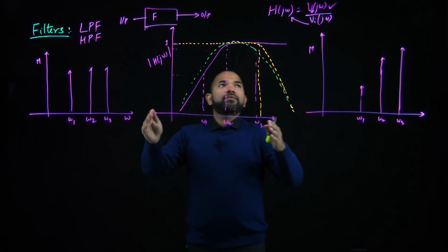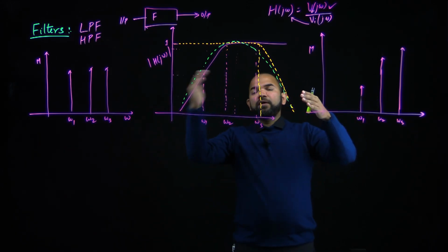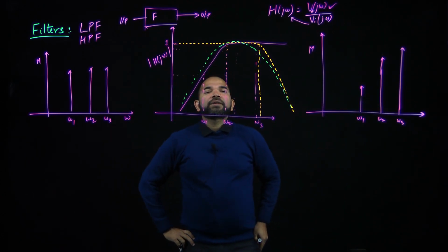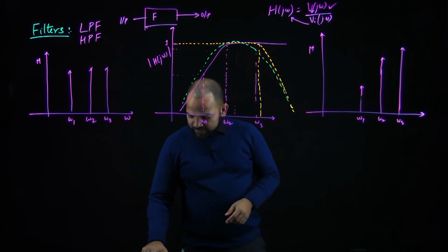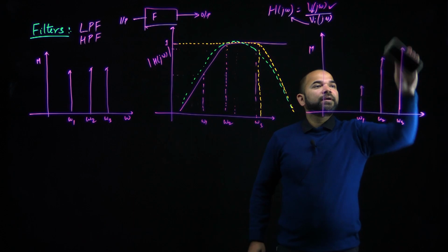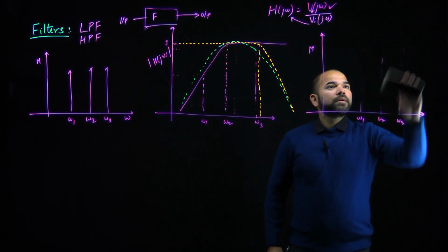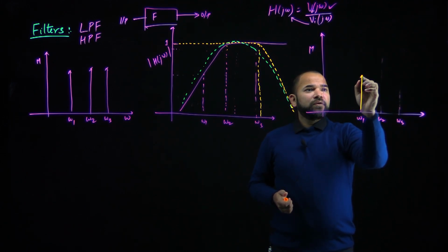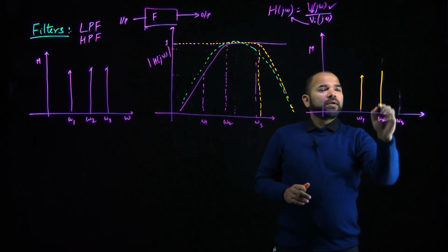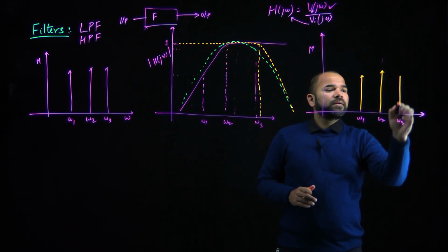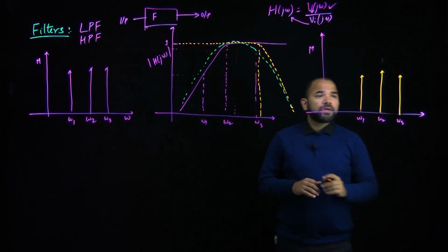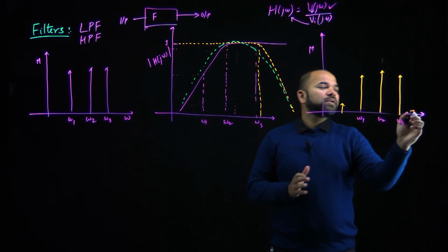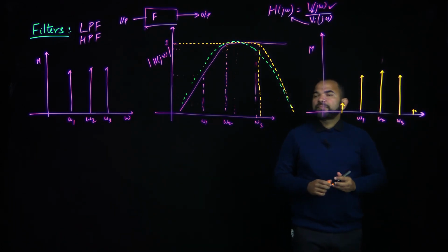In the frequency domain, if we multiply two transfer functions, a low pass transfer function and a high pass transfer function, then we can have something like a band pass filter characteristic. With the band pass filter, the output will have certain attenuation at the cutoff frequency. The middle frequencies are transmitted, and this is the cutoff frequency for the low pass filter. So this is the band pass response. If any signal is in this region, it would be greatly attenuated.